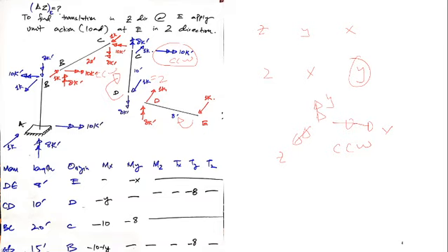Again, I have to balance this joint B. So 1 kip is balanced with 1 kip. 8 kip-foot upward is balanced with 8 kip-foot downwards. This 10 kip-foot rightwards has been balanced with 10 kip-foot leftwards. Finally, this one, again I have to balance this member. 1 kip-foot would be balanced with 1 kip-foot. This downward 8 kip-foot would be balanced with 8 kip-foot. 10 kip-foot would be balanced with 10 kip-foot. So I am done. You have to do a little practice to learn this.